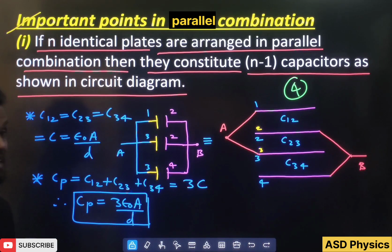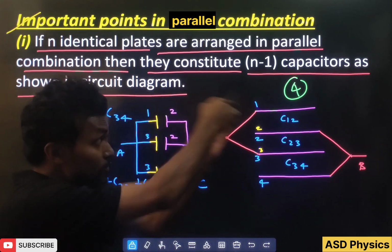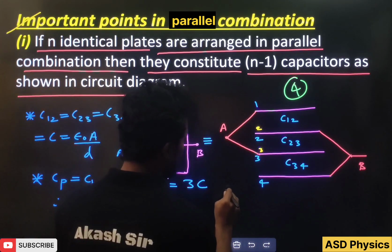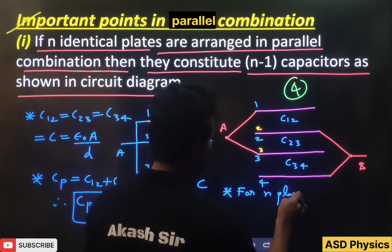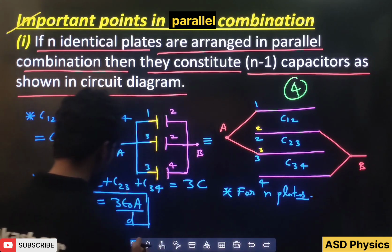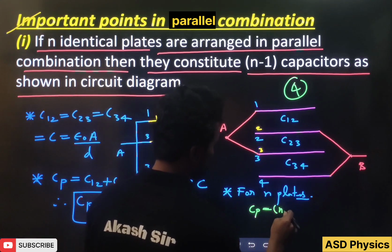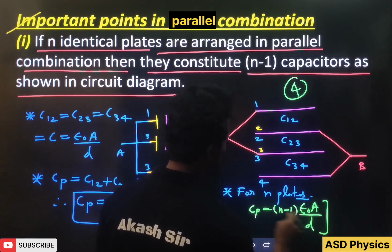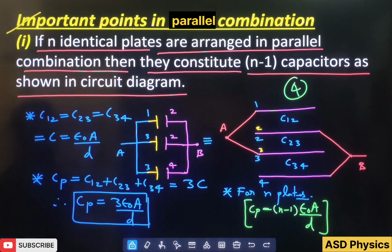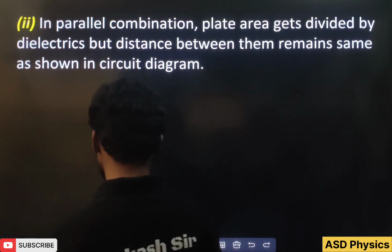But what are we getting? 3. That means we are getting the capacitance for 4 plates, but here we got 3. So if I write for n plates, what formula will come here? It is given by Cp equals n minus 1, epsilon naught A by d. So very well, we have done the parallel combination of the plates. Okay, great. Now students, let's see the next one.